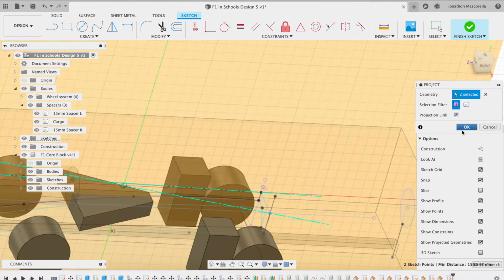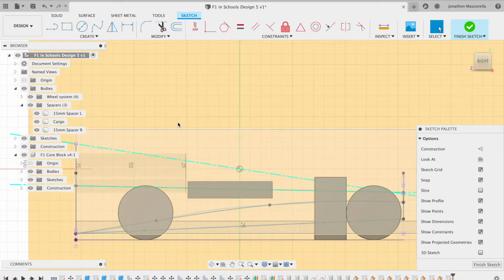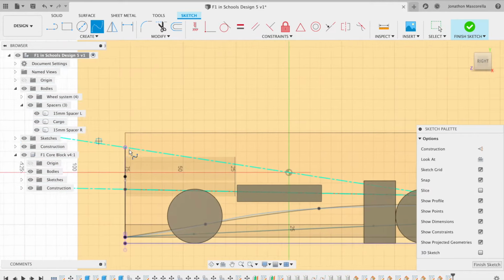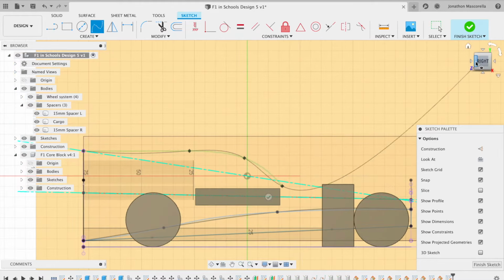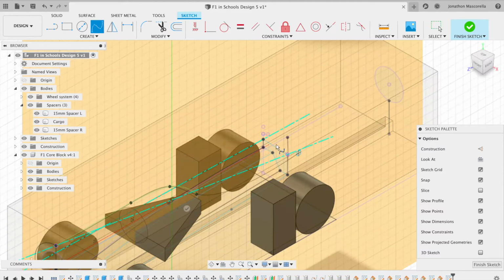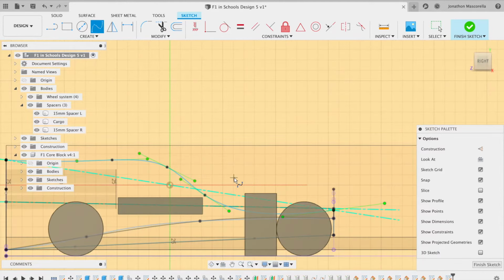I'm showing the block that I had brought into this sketch before, so that I have some point of reference to go around the canister, remembering that you have to have at least 3 millimeters clear of the canister from the body of the car, the outside of the car. And that's important for safety, but it's also an important aspect of the design requirements.